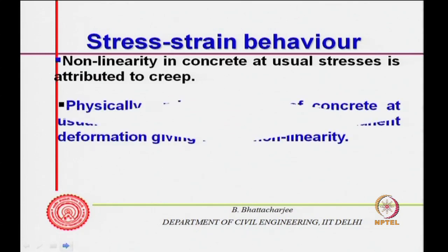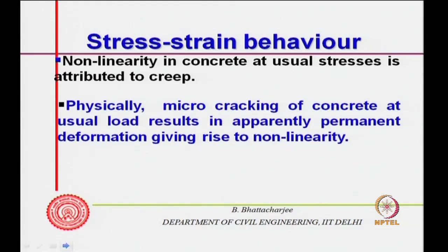Now, physically, of course, micro cracking of concrete at usual load results in apparently permanent deformation, and that is why it gives rise to nonlinearity. I mean, creep is one issue, but why finally? Micro cracking of concrete at usual load results in apparently permanent deformation, giving rise to nonlinearity.